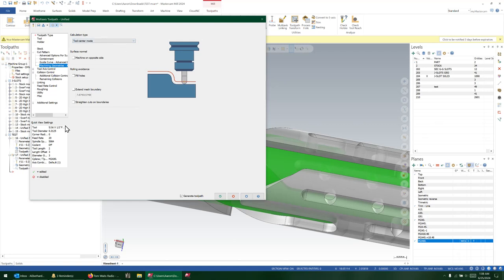However, it can't do that if you have a flat end mill or a bull nose or any of the other shapes. And this is what it was complaining about. So it was just saying, hey, you used a flat end mill and you were trying to use tool center mode, which is the default. Would you like to switch to contact mode? So I could have just hit yes and continued, but I wanted to explain that. So let's apply that now, see what we get.